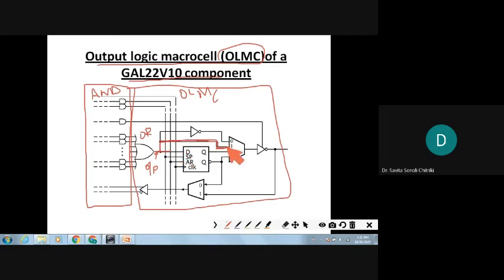So now this is the pure output line. Directly the output is connected to 1. What is the symbol for? This symbol is what for? Multiplexer. Okay, this is the symbol for multiplexer. Good. So now the multiplexer has the inputs 0, 1, 2, 3, means what? 4. So how many select lines you need? 2. Very good.